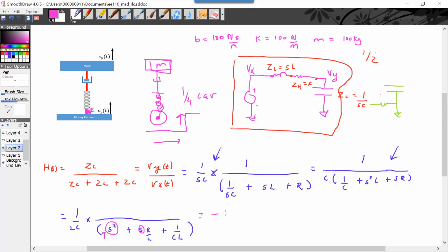Now, what you might not realize is that this is completely generic. We have this equation. You can see 1 over omega naught squared is LC, and 2 times the damping coefficient over omega naught equals R over L. Now this is strictly for when these elements are connected in series. Not every RLC circuit will have this same denominator.